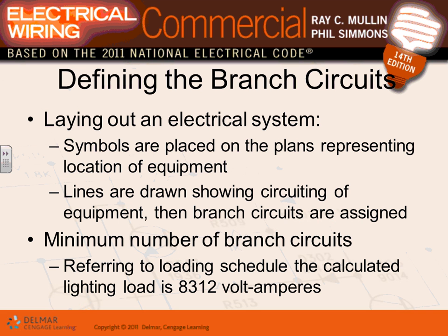And then when you group them, lights are continuous load. I'm telling you right now, lights are continuous load. So can you load a 20 amp circuit more than 16 amps? No. So from the get-go, you're limited to 16 amps. Because we group them, always group them together. Remember that calculation that we did? So you can't pull more than 15 amps. So you are looking at 15 amps out of a 20 amp circuit. That's your limit on lights.